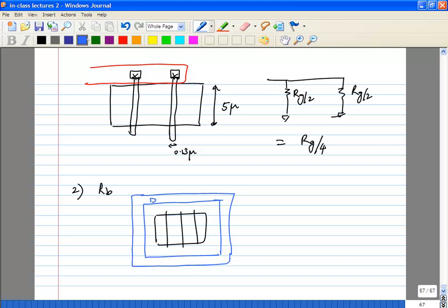This is actually a substrate ring, a ring around the transistor full of substrate contacts, because RF transistors are especially sensitive to substrate effects. You try to make sure it has a very good substrate, because the actual connection to the substrate may be very far away. So you connect it here and then connect it on metal to a good ground.